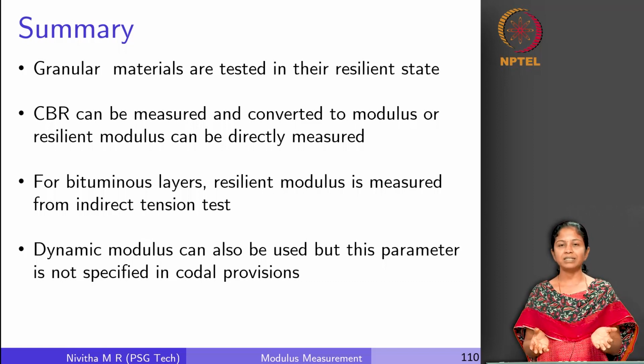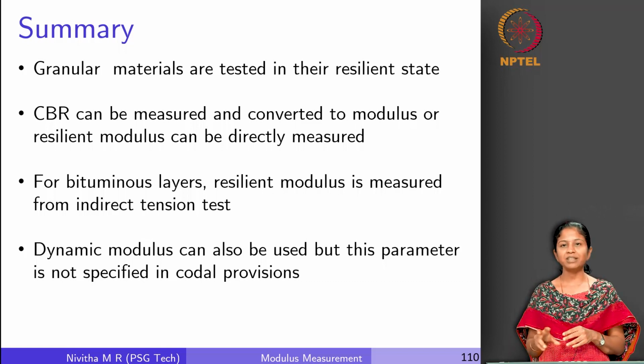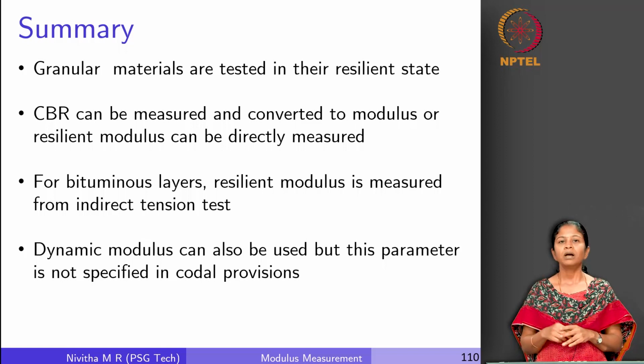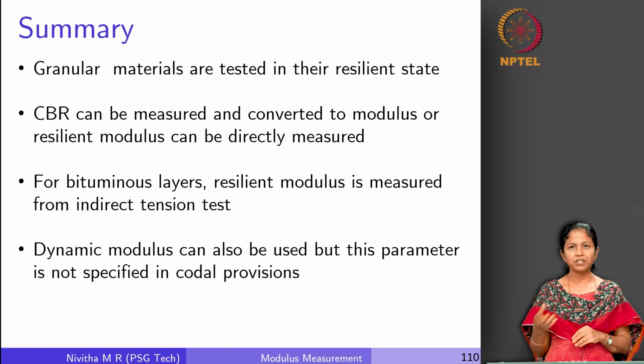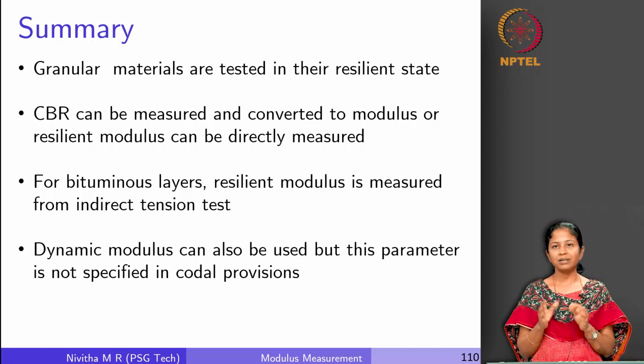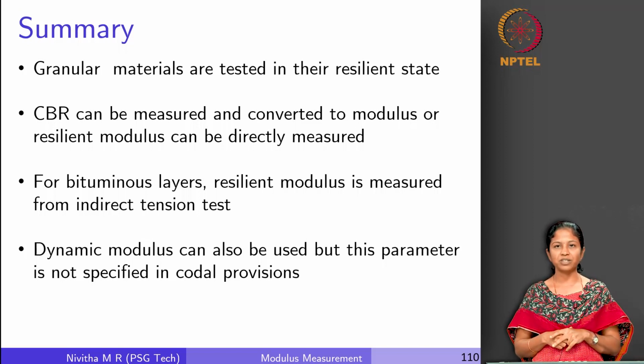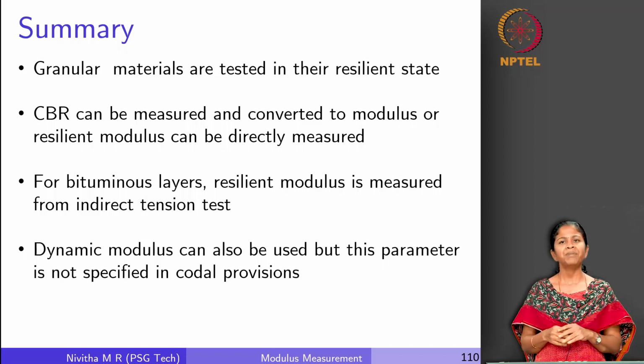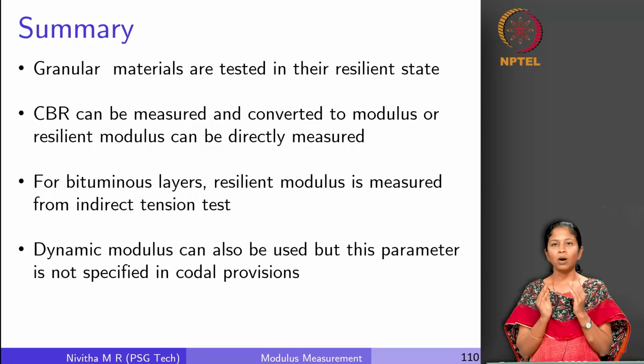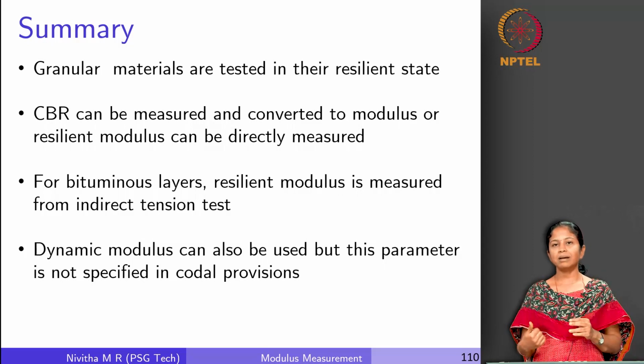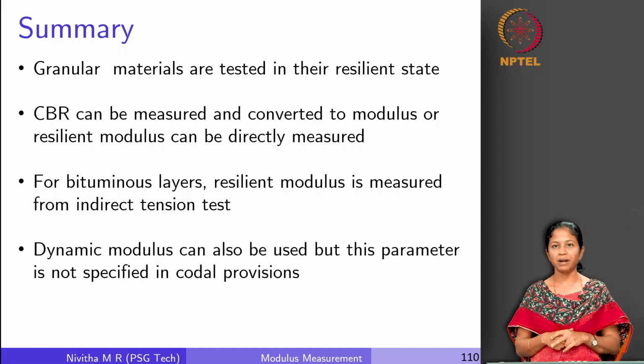The test temperatures of interest would be between say 5 degrees to 40 degrees. In this temperature range, there are many studies which have reported that it is hard to identify any resilient state. So, they have also suggested provisions on how to mitigate these issues. Most of them use a constant strain rate. This is one of the challenges associated with this test procedure. There are a lot of other issues as well, but for now we are only interested in how to measure a modulus and subsequently evaluate the effect of climate and environmental effects on these modulus parameters.